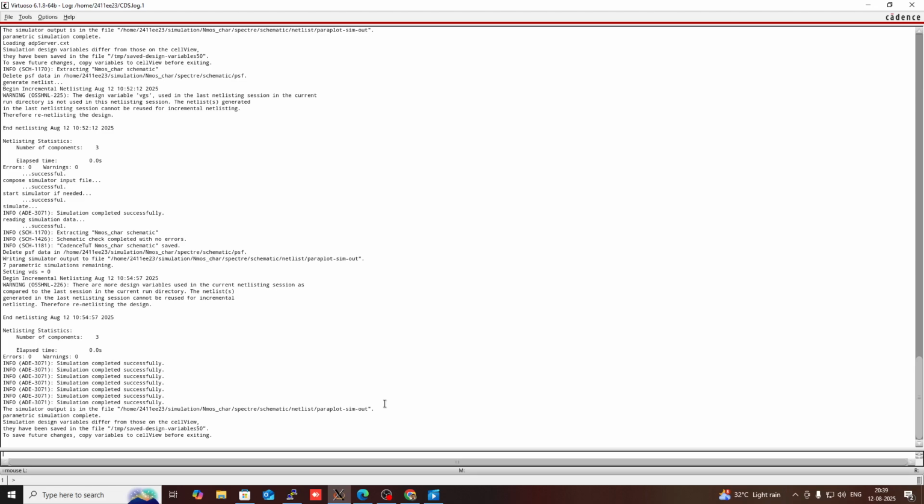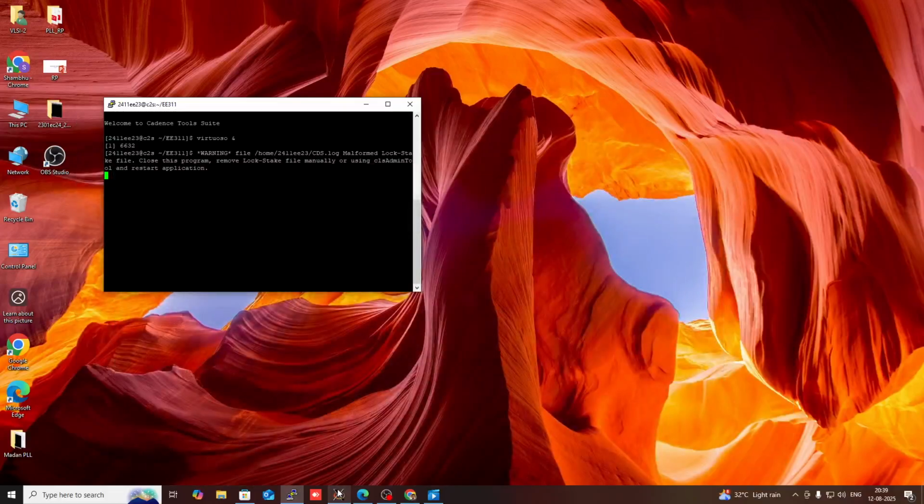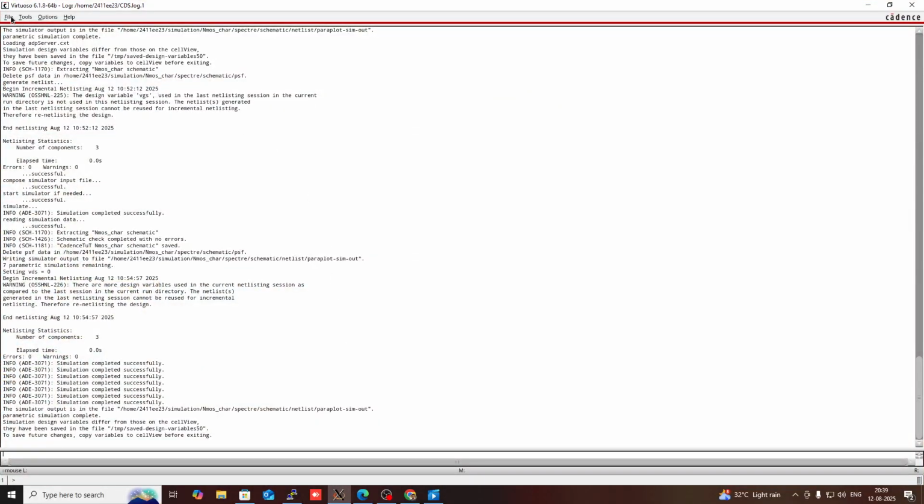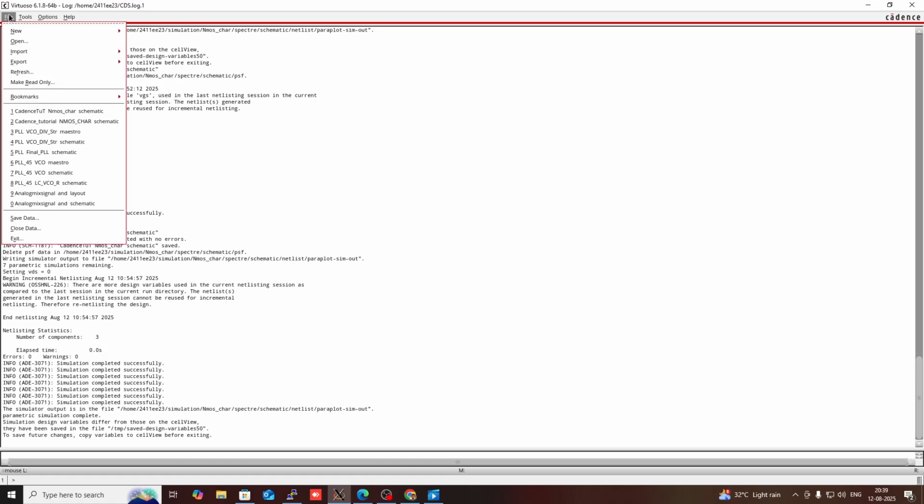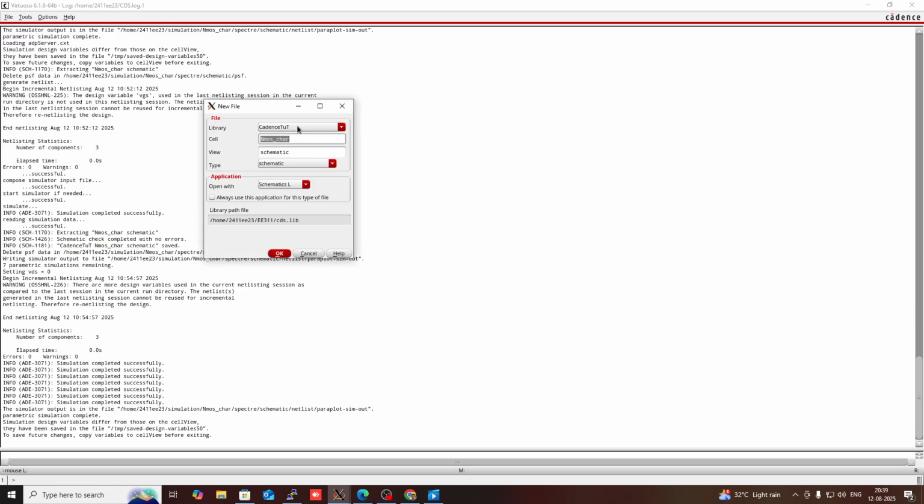So in this lecture series of Cadence, in this video I am going to explain about the ID versus VDS plot of PMOS. So for that I am going to create a PMOS cell view. In File, go to New, then in Cell View again go to Cadence tutorial library, and in that I am going to change this cell name as PMOS characteristics.